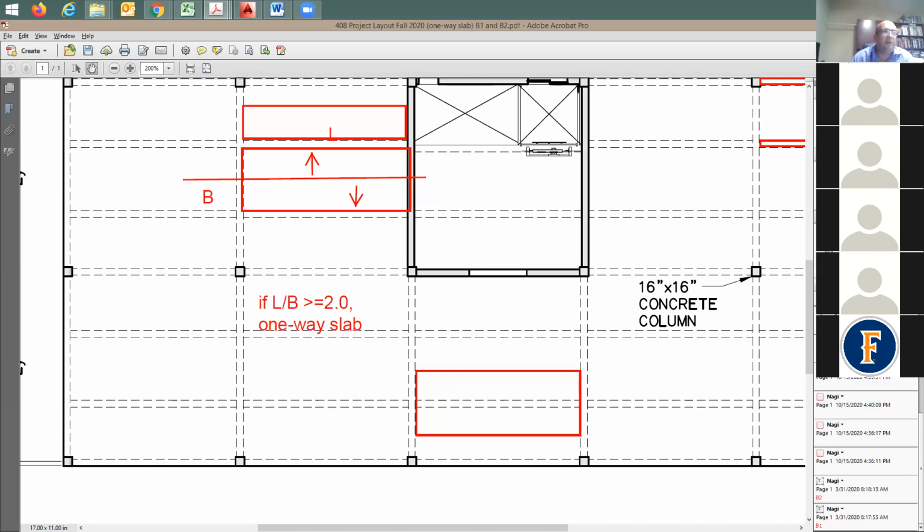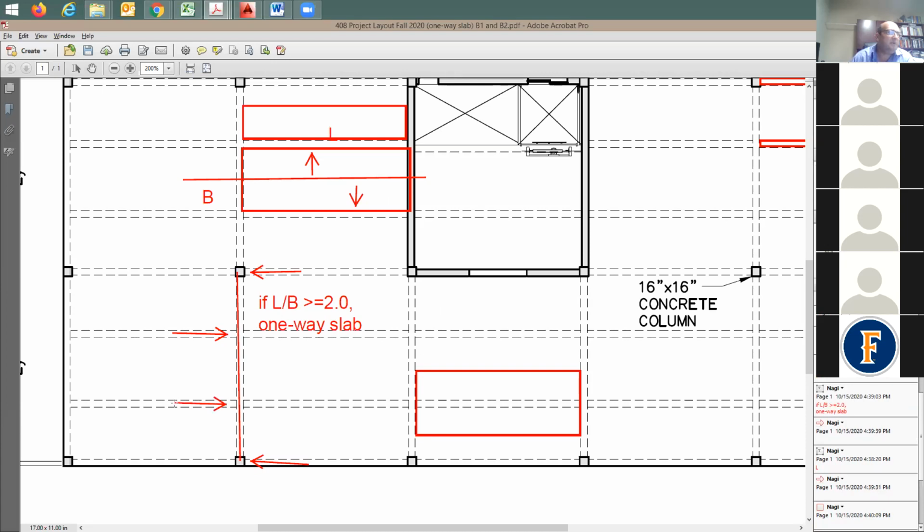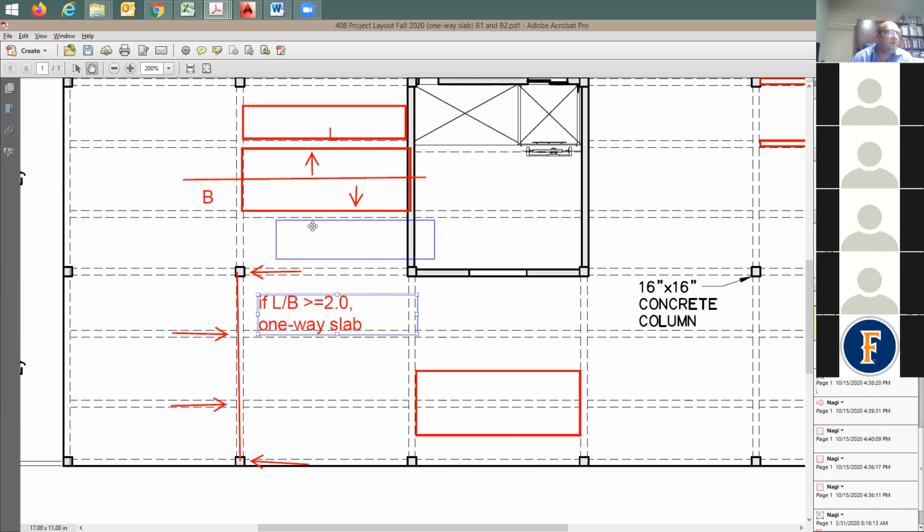If you'd like to model this girder, you're going to treat it like a beam like this, and then you're going to have two supports, like roller support or hinge support, and then two point loads that come to it. This is going to be a point load coming from this beam, and a point load coming from this beam. How about this beam here, what's supporting these beams?